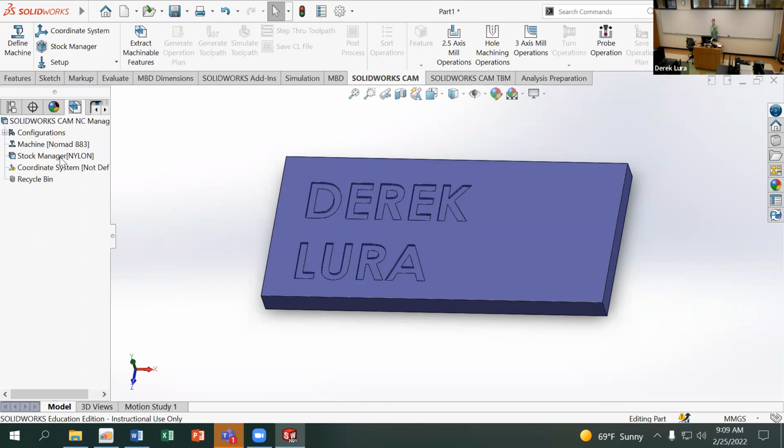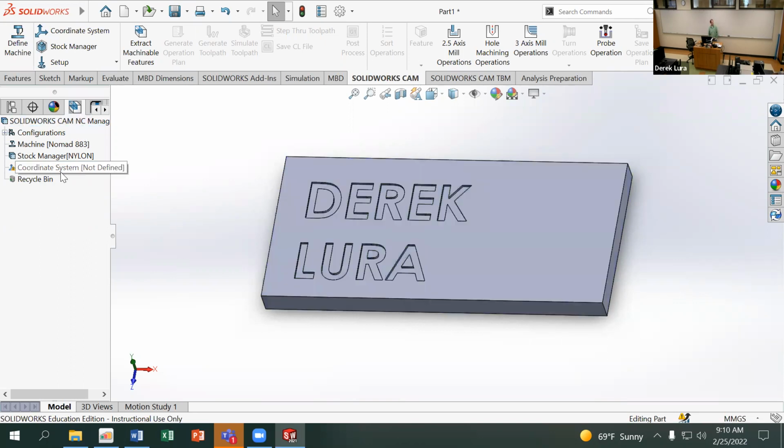And then SolidWorks will say, okay, what's the difference between the stock and the geometry I want for the part? And it'll find an operation to do just that, right? So again, you can get complicated. Most of the time your stock is a rectangular block to start off with, right? So that works out good for most of the stuff. Again, obviously my stock is not a rectangular block, but it's close enough, right? I'm not going to mill out the external portions of the case. I'm just going to do my name. Make sense?